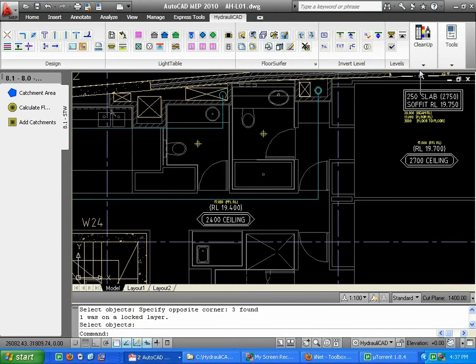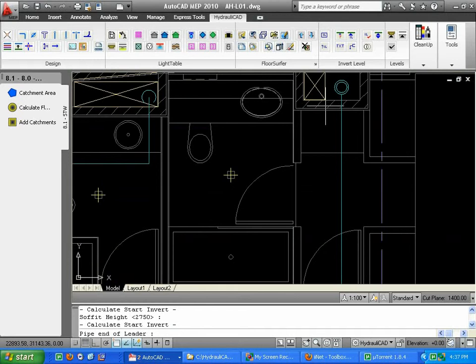So that's the height. We can put in an under slab invert level, which is a B, which is quite handy if we have a flat slab and we're doing a bit of coordination. We put in 1.65 pipe OD, spacing is the same. Soffit height doesn't really matter, but we can put that in. We'll put start under slab, and then we pick here.